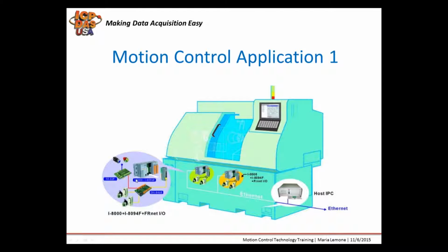The user inputs what they want to do into the HMI, and it talks to the PLC, which performs the different recipes and operations specified by the program. You can also communicate with other machinery over the Ethernet bus to get information back, and the status lights are turned on and off at the top of the machine based on the operations.